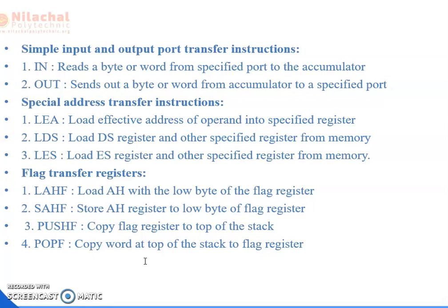Next, IN reads the byte or word from specified port to the accumulator, and OUT sends out a byte or word from accumulator to a specified port. Next, LEA means load effective address of operand into specified register. LDS, load the DS register and the other specified register from memory. And LES, load the extra segment register and other specified register from memory.